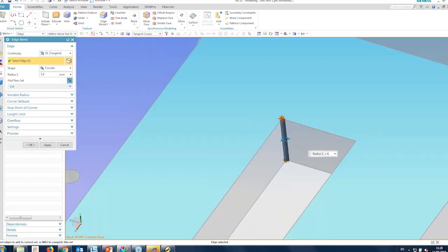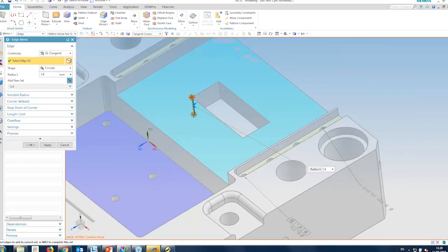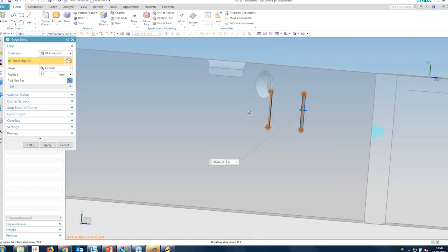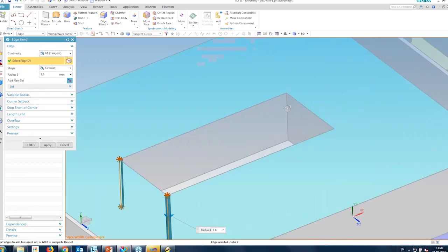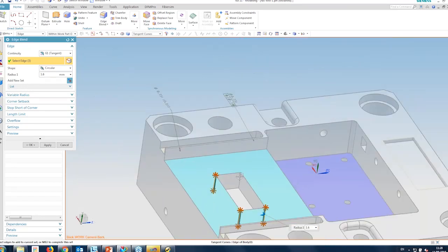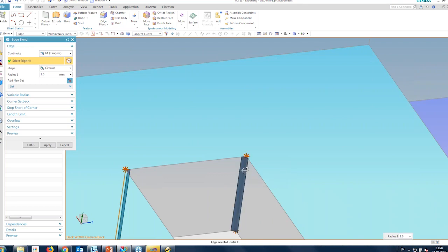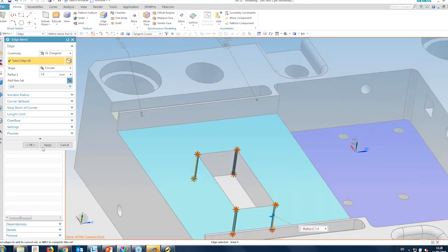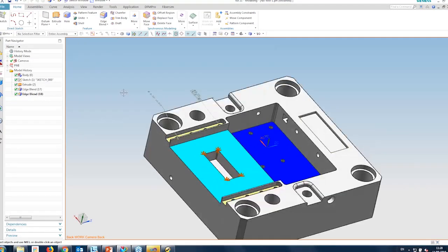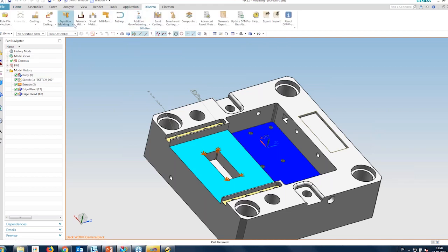So as per standards, to achieve a depth to side radius ratio of less than or equal to 16, that's the standard out-of-the-box guideline which is supposed to be followed, and again that is configurable as per your requirements. But in order to achieve that particular depth to side radius ratio, I need to either reduce the depth to below 22.4 mm, or increase the radius at this particular sharp edge to at least greater than or equal to 1.5. Right now we have added a radius of 1.4 at this particular area because that was feasible for the depth of this particular pocket.